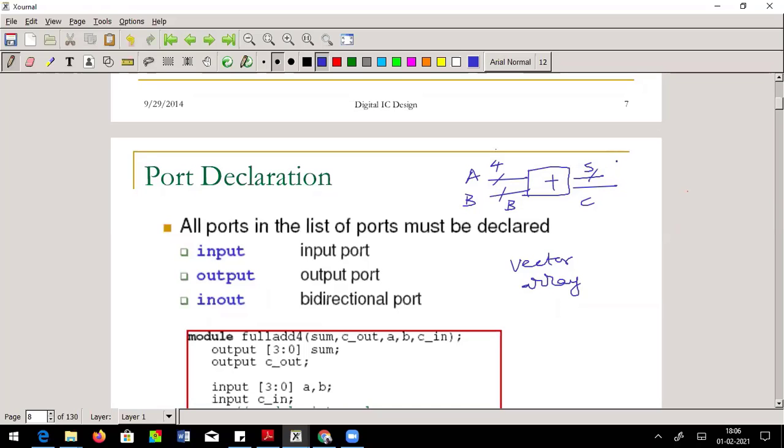So this is expected to be 4 bit and this is expected to be 1 bit, so totally it will be 5 bit. Now, if it is a single bit, you have already said input so and so variable, output so and so variable. How do you declare this many bits? The way to do that is to say input, again in small letters, input [3:0].